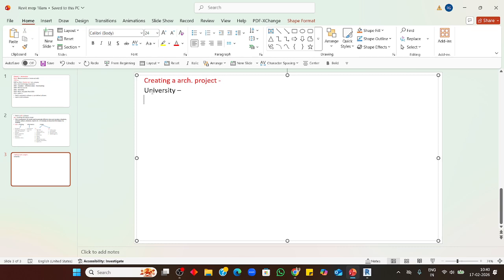There's the basement. Forget the basement right now, just floor to floor height. How much? 12 feet minimum for central AC, if it is there. And plinth height, no, no, it's a project. I'll take the plinth height as 4 feet.